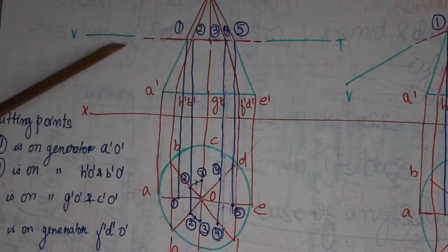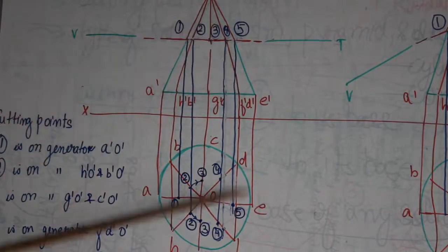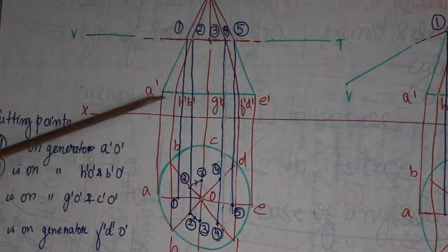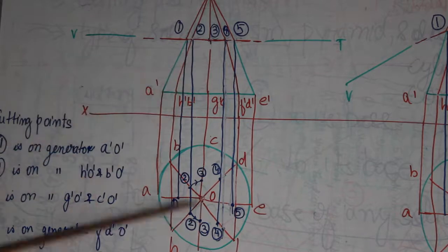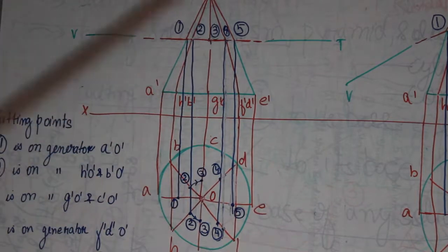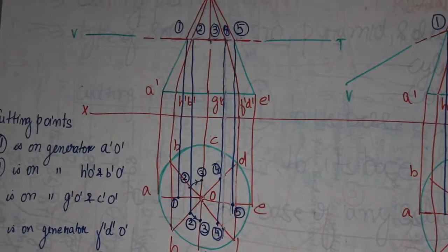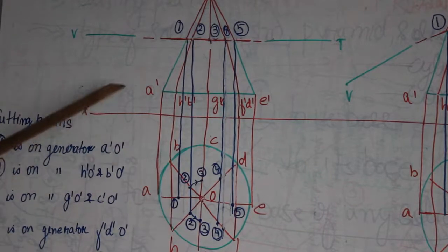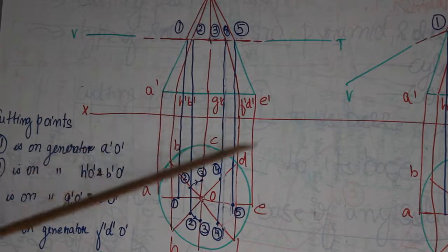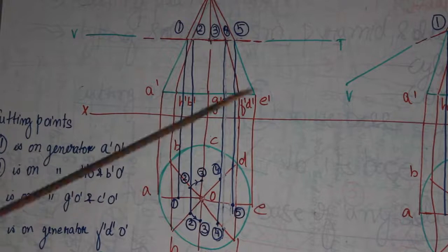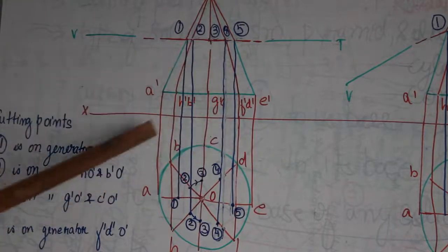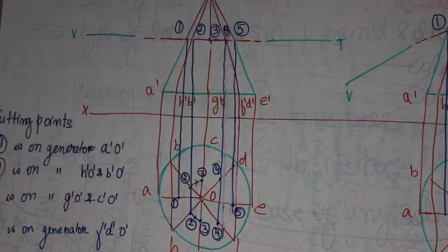All the lines made with the green pen are dark lines, and all the lines made with the red or blue marker are light lines. You have to practice this: all light lines shown in the drawing should be of the same consistency and strength, and all dark lines should look the same.